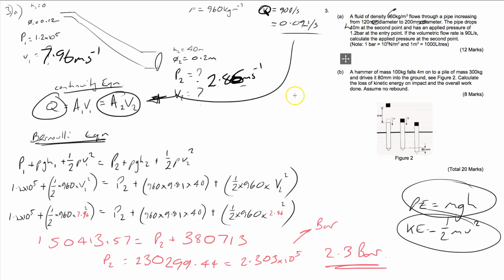Excellent. That's Bernoulli's and continuity equation. Generally, those two equations are used in tandem. I recommend plugging in all your data into the Bernoulli's equation, working out what you're actually missing, typically velocities, and then using continuity equation to deal with it from there on.